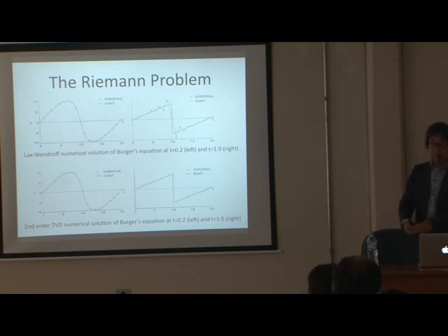The interesting point is that in artificial viscosity, the function that you use is such that the correction is big at the discontinuities, because you have this velocity shear. You get the average, and then in regions where the discontinuity is smooth, the correction is really small because you have no discontinuity. So the correction is much smaller than the numerical error. So that should be fine.